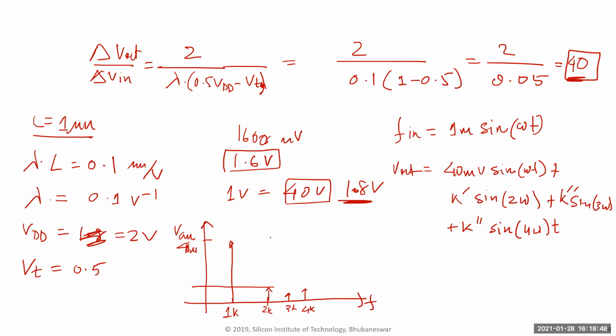If you tell me I can handle only minus 30 dB, then depending on the size and the nonlinearity of the transistor, a delta V in of maybe 100 millivolts is fine, right? You plug in the values and see how much nonlinearity. If you say no, this is too much because I'm doing a high fidelity audio amplifier, then you say, okay, I want minus 90 dBc for all the harmonics, right?